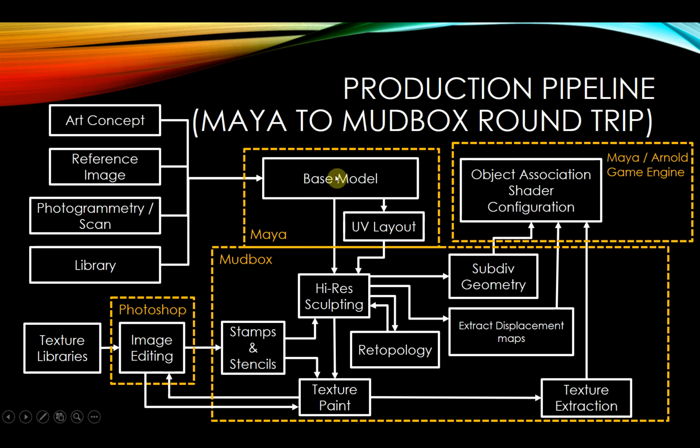It needs to be a clean mesh with no non-manifold geometry inside it. And when you press 3, you should get really nice smooth geometry, and any edges that need to be hardened also need to be reinforced in order to support subdivision smoothing.